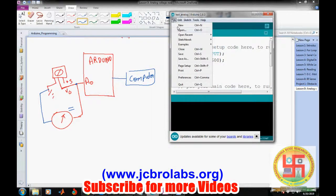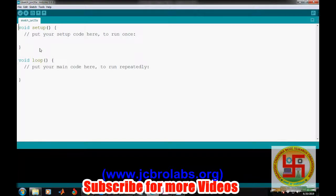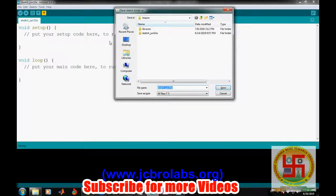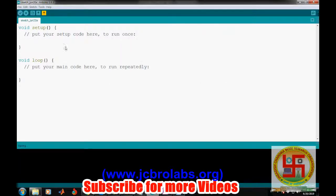First task is to create a new file. First task is to save it. Let's say on desktop, as lesson 9. Let's save it. It is saved. Let's check whether Arduino is connected. Yes, Arduino is connected. First of all, we need to decide the pin mode of the pin which we are going to set. So A0 should be set as input.